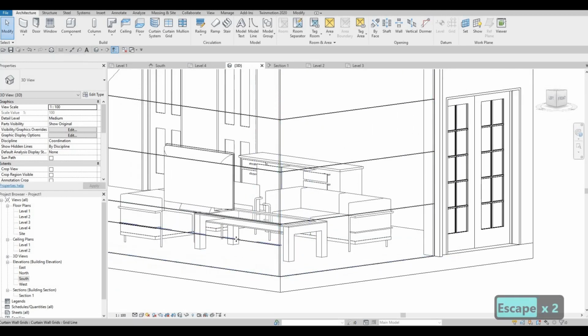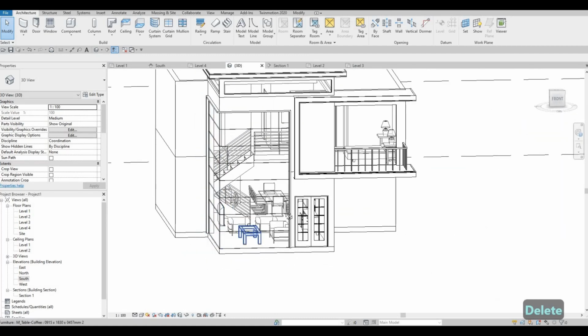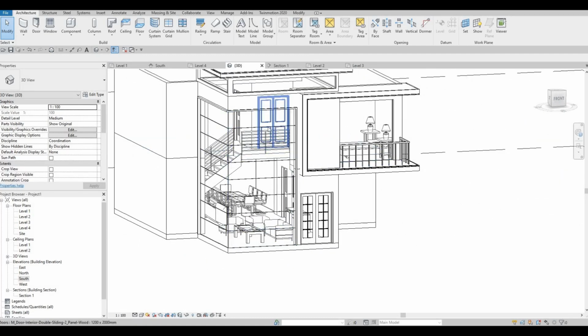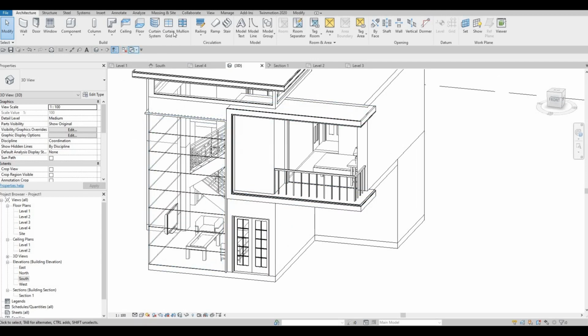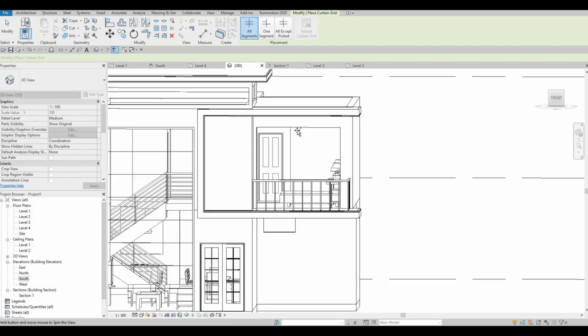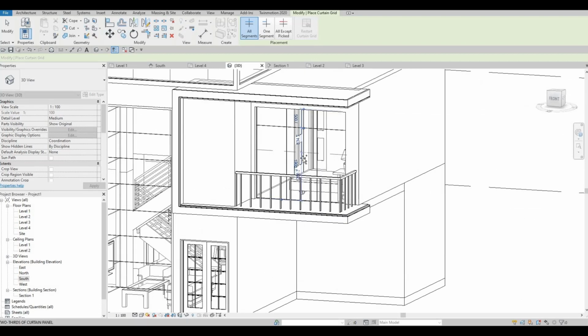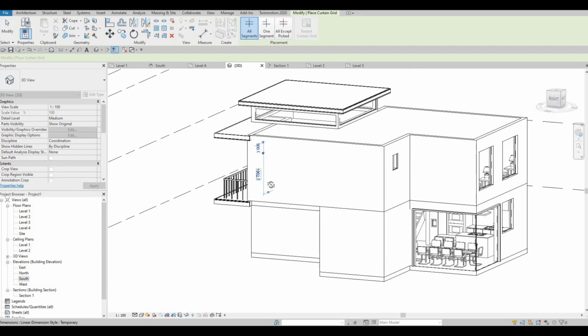And then here you just need to delete this one. There you go. So we're just gonna add in the mullion on this side, like that. But for here, let's add this one. Let's divide this as 3, and then let's add in 500 at the top. So we could have a door like that later on.